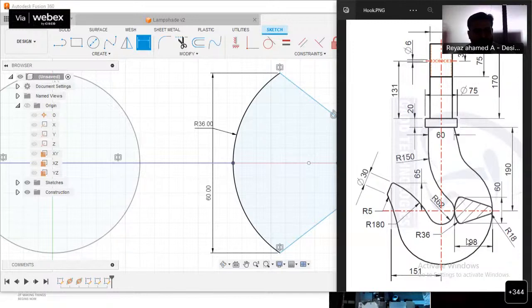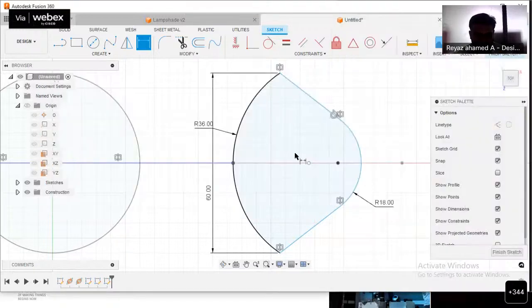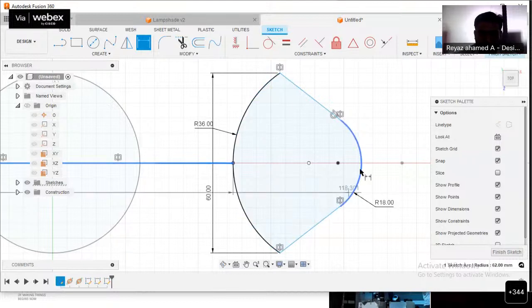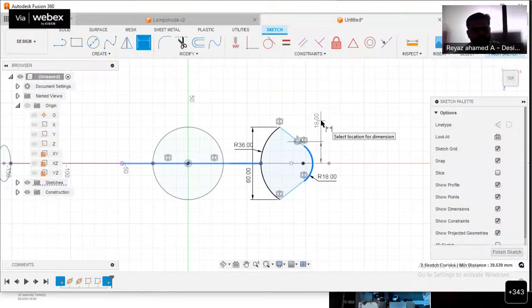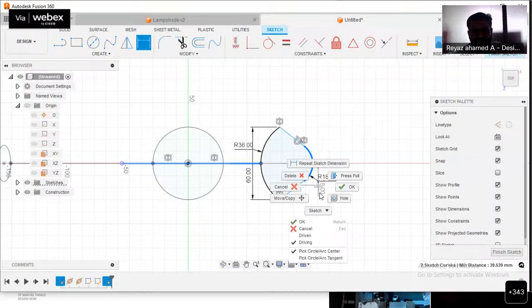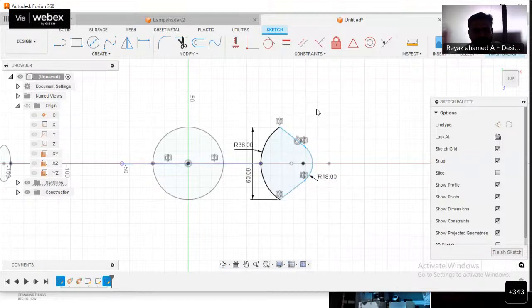Go with the Alt Tab option. So choose this end point. So that is not at all a problem. Just let me click on this end point. And then have to choose this point actually. If you click on this, it shows some vertical distance, right? But it should not be shown like that. It should be arc tangent. Let me choose it. Go to the line dimension option.